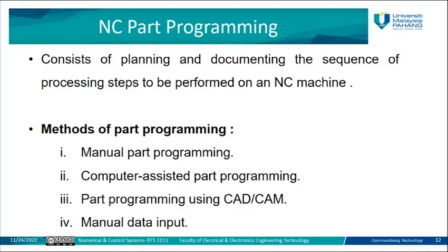The most commonly used method nowadays is CAD/CAM programming. By using CAD/CAM, the designer will create the 2D drawings. They make the drawings for the product using 2D. They define the dimensions, the tolerance, where the circle and the hole are, what the diameter is, and so on.